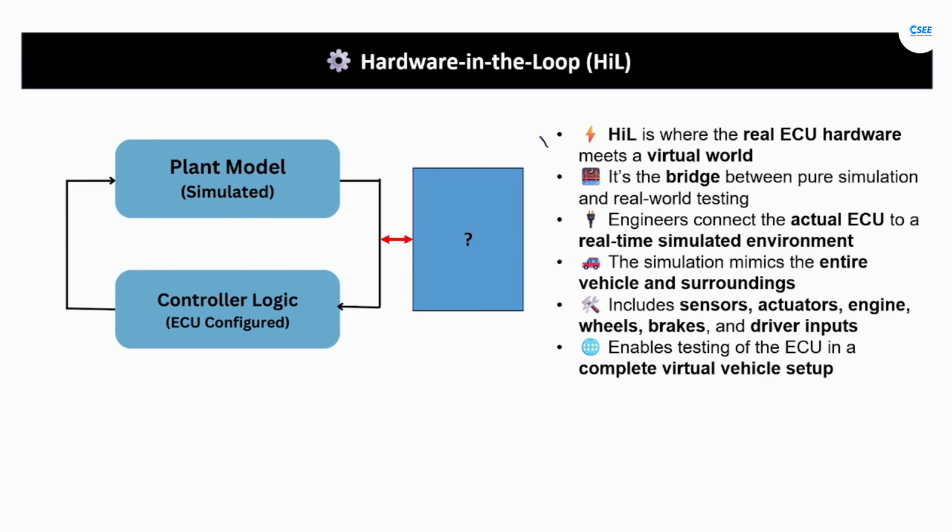HiL is where the real ECU hardware, the same one that will go inside the vehicle, meets a virtual world. It's the bridge between pure simulation and real world testing. This is where engineers connect their actual electronic control unit to a real-time simulated environment that mimics the entire vehicle and its surroundings: the sensors, actuators, engine, wheels, brakes, and even driver inputs.